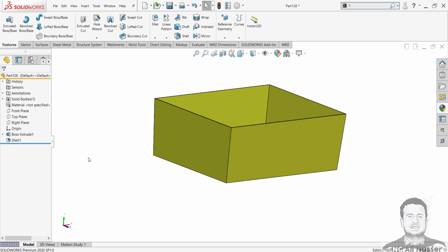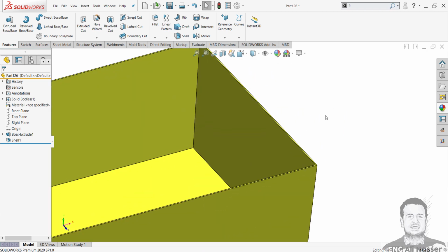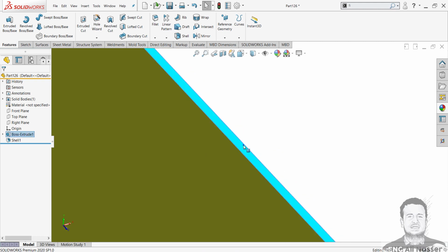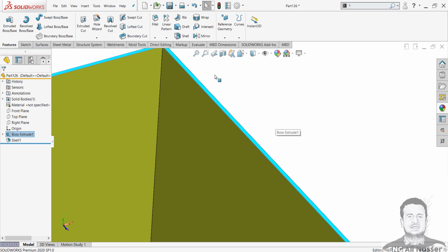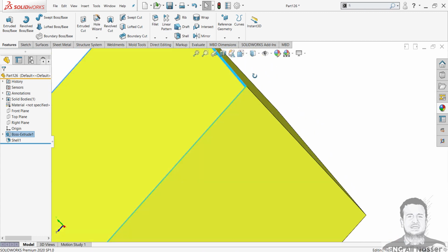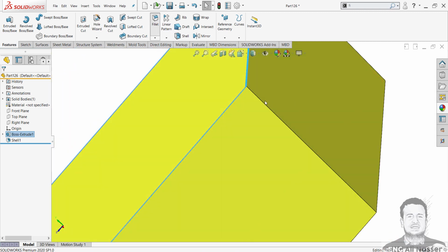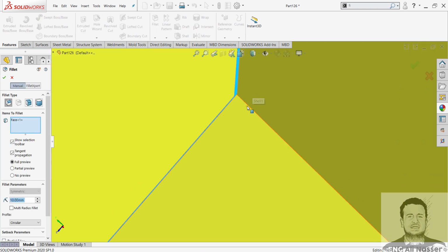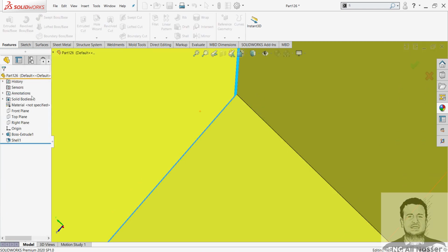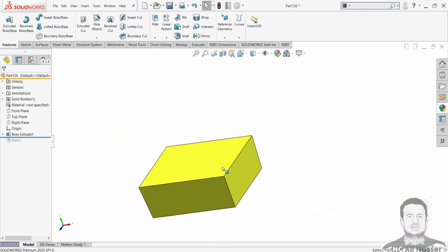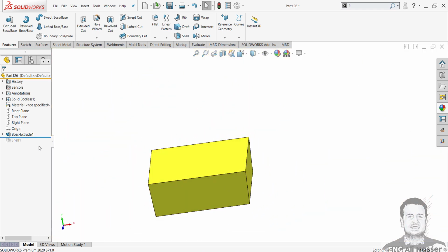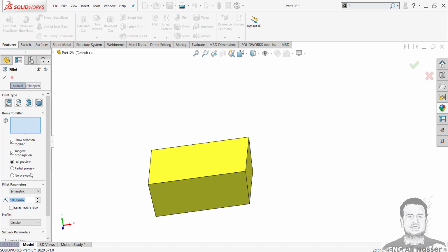Now we will create the cover for the tank. Let's start with this face, but before that I will create some fillets for the main body of the tank. Let's make them before the shell, to offset the fillets when applying the shell.